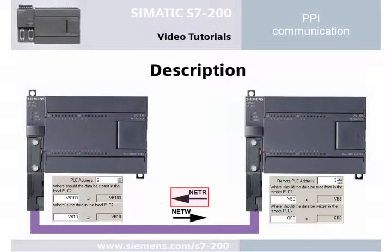Using the NetR function enables reading a data area from a remote PLC and storing it in a selected data area of the local PLC. Using the NetW function enables writing a data area from the local PLC into a selected data area of a remote PLC. This enables communicating with up to 24 PLCs per port via the instruction wizard for NetR, NetW.